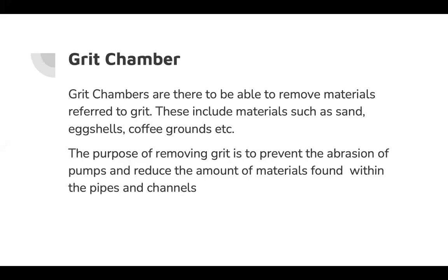So the grit chambers are there to be able to remove materials referred to as grit. These include materials such as sand, eggshells, coffee grounds, etc. The purpose of removing grit is to prevent the abrasion of pumps and reduce the amount of materials found within the pipes and channels.